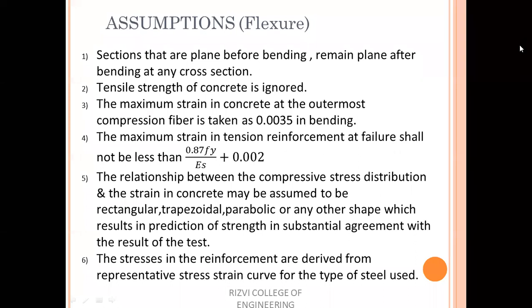Okay, I had mentioned that out of plane bending we are not considering. Suppose you have a beam and that beam will bend. After bending, the top portion will be in compression and the bottom will be in tension. Again, if you take a section at that point after bending, its strain will remain uniform. That means the strain profile will be linear. That is the meaning of plane sections before bending remaining plane even after bending. I hope this is clear to everyone.